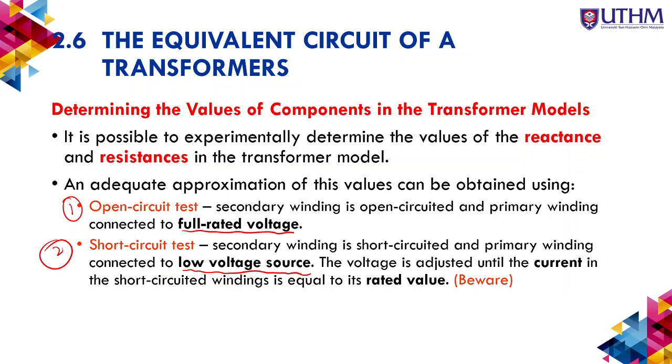Even though you use a low voltage, the process is short circuit, so the current will be higher. Otherwise, if you use the high voltage or full rated voltage during the short circuit test, for sure everything will become barbecue, it will burn up.